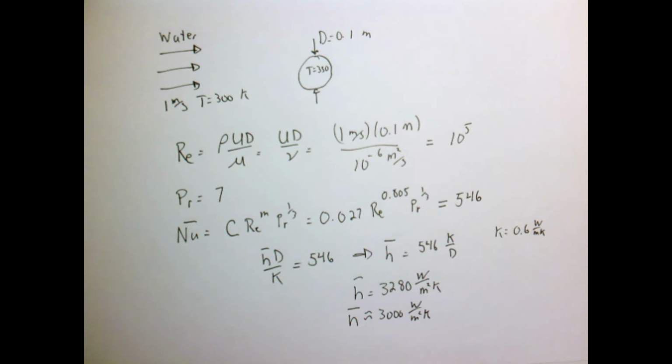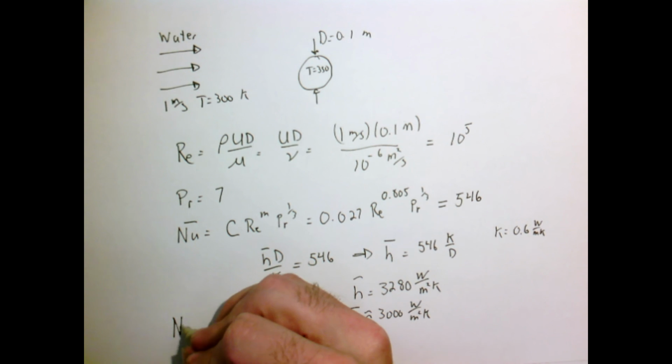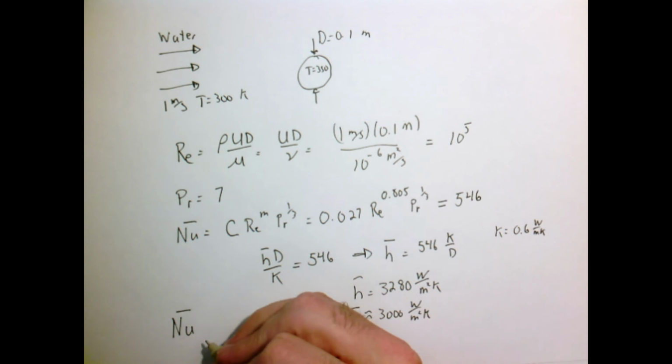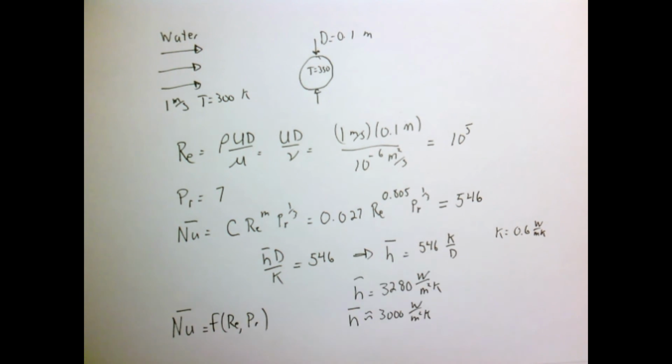And again, the magic comes from not any of these particular numbers here, but that by analyzing our equations, we get the average Nusselt number is a function of only 2 dimensionless parameters. So it allows us, just like we've seen before, to do a limited number of experiments to be able to explain a wider range of physical or dimensional quantities of heat transfer.